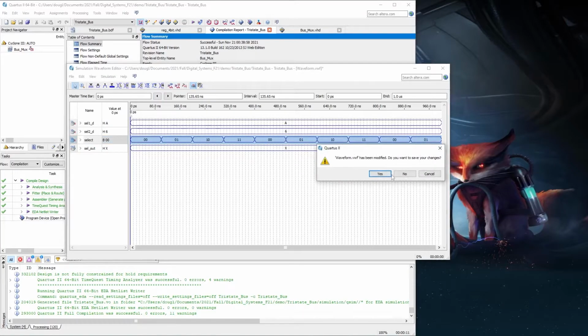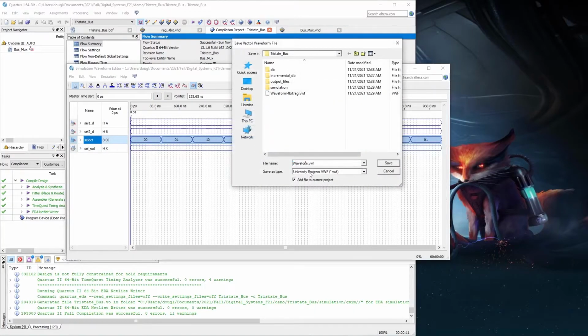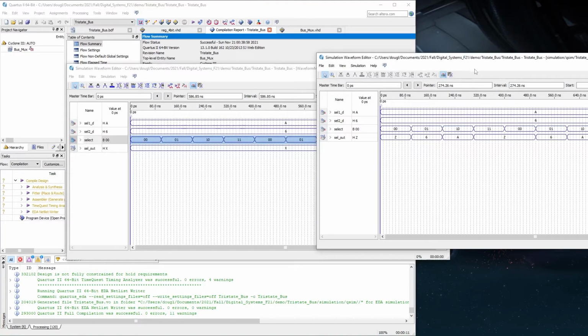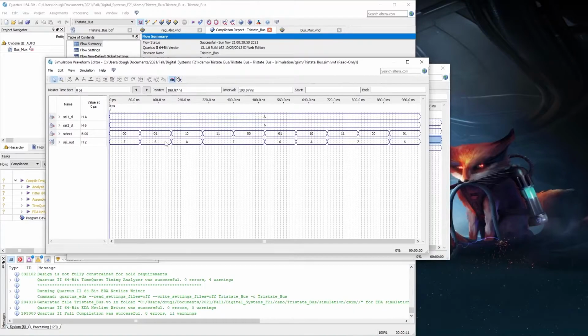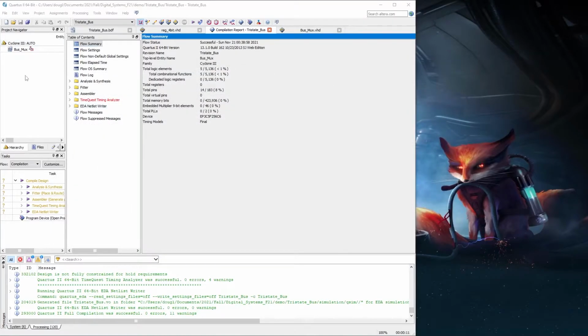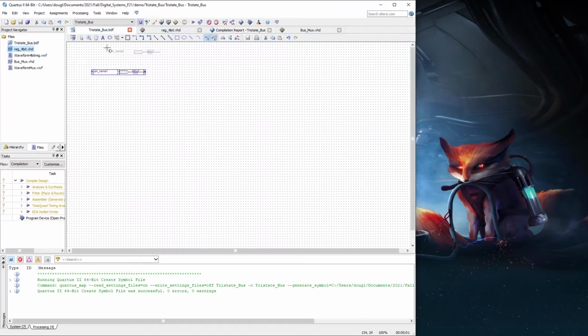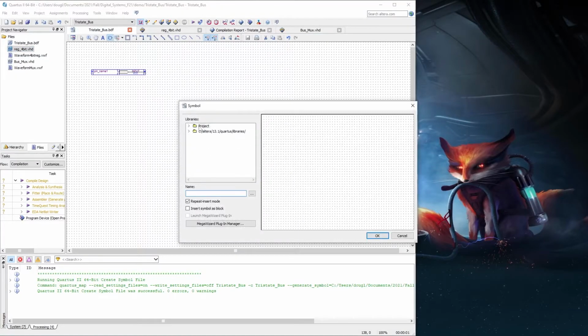All right. So go ahead and run this as the mux. And you can see here, Z6A, ZZ, everything where I want. Looks like it's going to work. So for this, what we're going to do now is we're going to go back and set that as the top level entity. The bus mux, I want to create a symbol and file. I'm going to create a symbol and file of that. And let's go ahead and add our entity, our stuff.